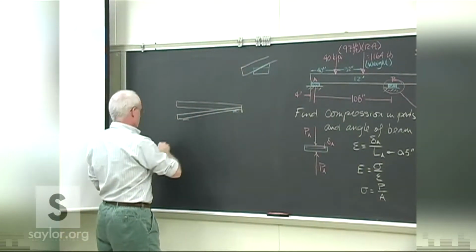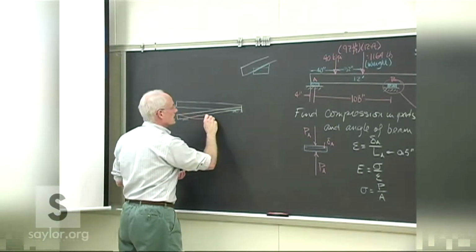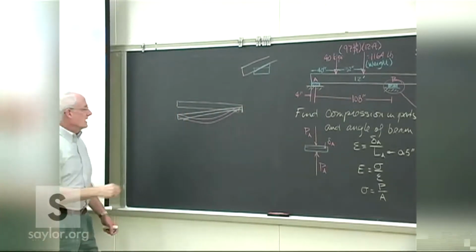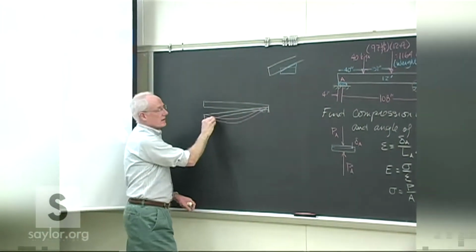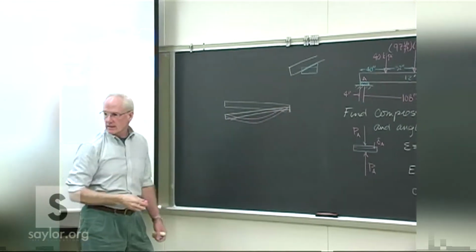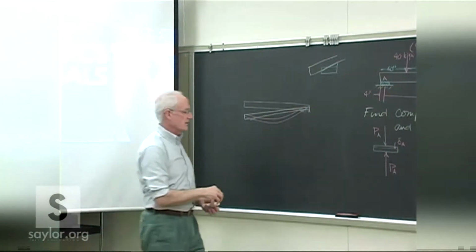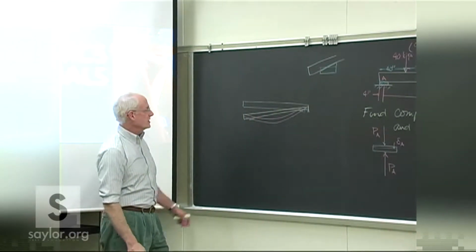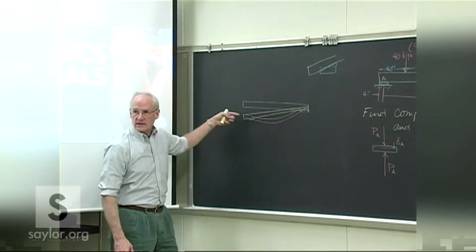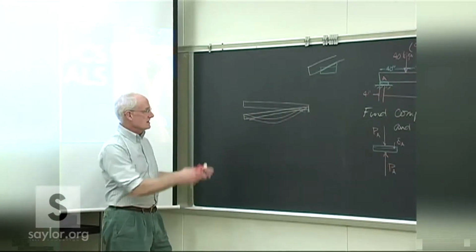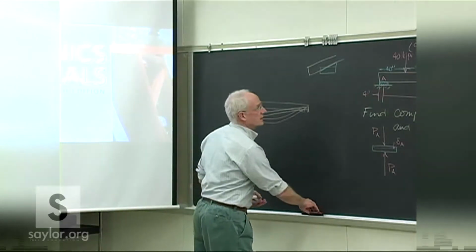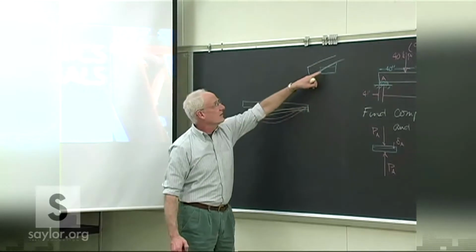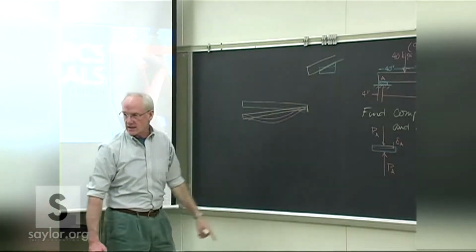The beam itself will deflect something like this, again, very, very exaggerated, giving a different angle here than over there, and we'll also be able to take those into account as we look at that kind of deformation as well. We're assuming through this whole thing that this beam is rigid and does not itself deflect because of the transverse loads. We're simply looking at the compression of the pads themselves. So there's actually two angular effects, and we're ignoring both of them at this stage.